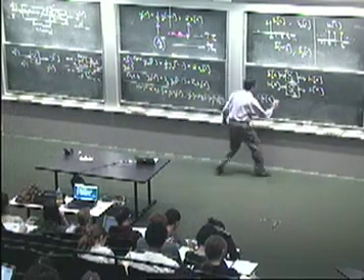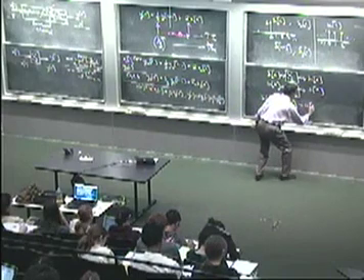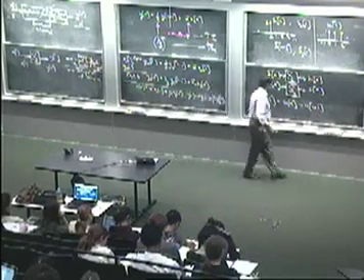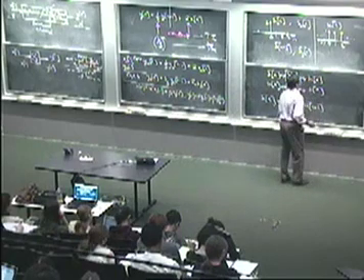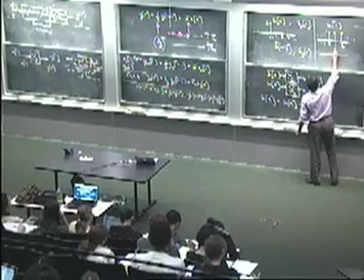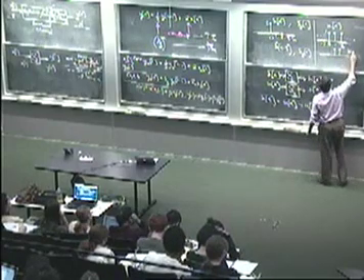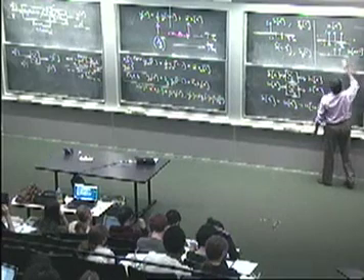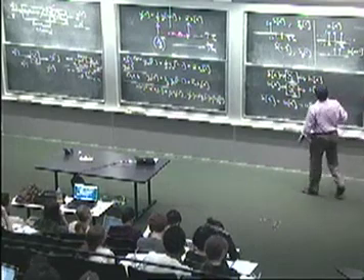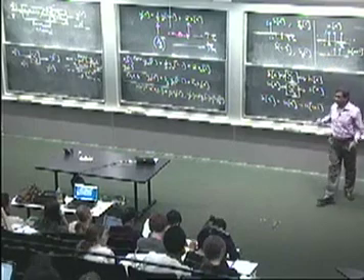Okay. Would it be, you said un minus un plus 1? Or is it un minus 1? N minus 1? So what we're saying is, take this unit step and then subtract from it a unit step delayed by 1. Okay, so here is u of n minus 1. If we took the unit step and subtracted from it a delayed unit step, delayed by 1, the result will be just that value 1 at time 0 will survive, everything else will cancel out. Right? Is that what you had in mind?